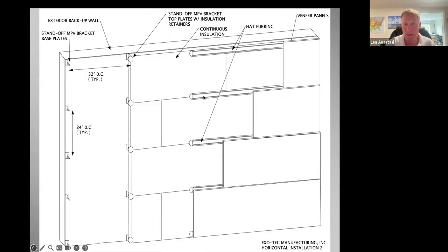I've had a couple of contractors in Massachusetts who are kind of adamant: I want this at 2 foot on center, because this is what our guys in the field are used to. So not only can we attach the panel, we can do the filler strip also on that. I said, if that's the case, you can open up your spacing horizontally to 32 inches and you're still getting that one bracket, 3/8 diameter piece of steel going through the wall at every 5.32 square feet.